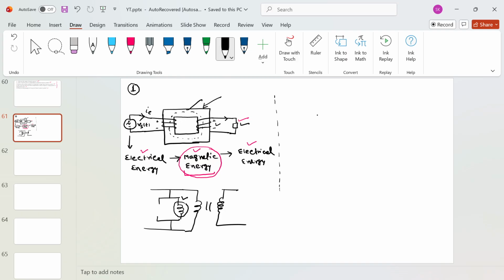See, if you look at the induction motor at starting, the equivalent circuit of the induction motor and the transformer are the same. Later on the frequency of the rotor circuit changes, and accordingly that effect can be considered in the equivalent circuit. But if you see the per phase equivalent circuit diagram of the induction motor, you will see this sort of equivalent circuit diagram.